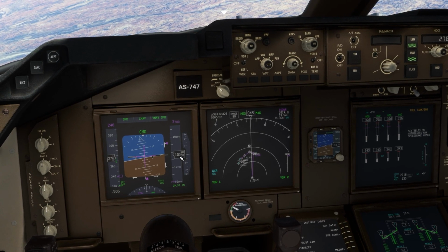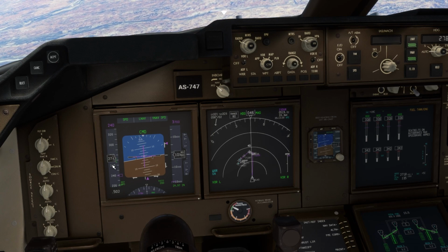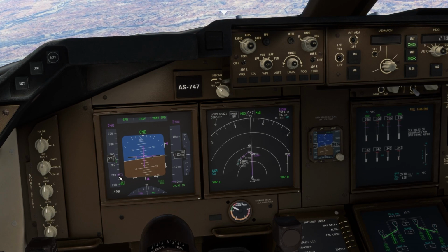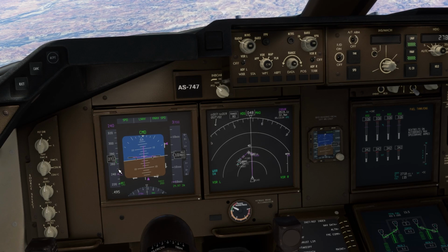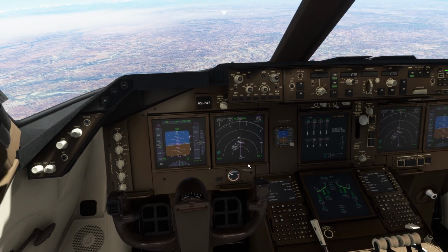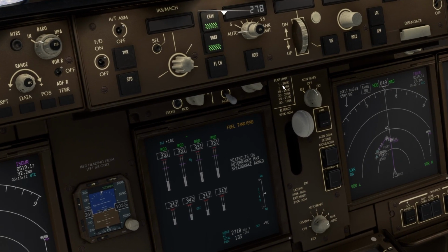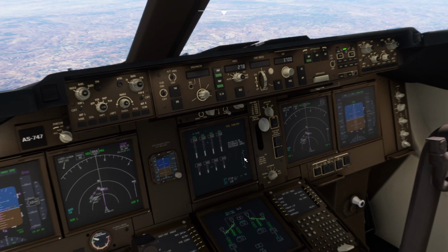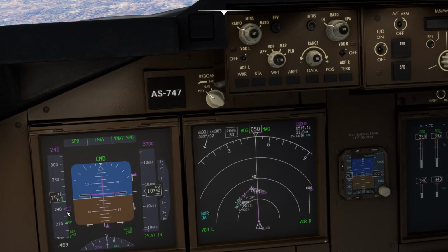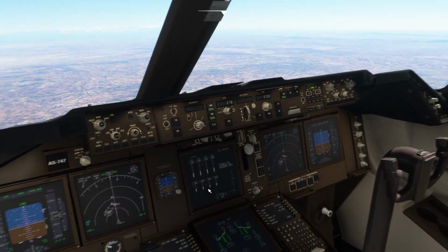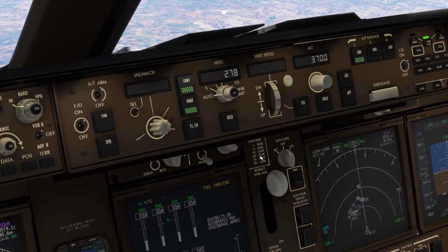Right now, as you can see, the plane is at 10,000 feet. That's why the speed is reducing, and it will be at 240 knots. And then once the plane is at 240 knots, the descent will start again. With this, I would just like to tell you the speed limits for different flap positions. At 285 knots, you can set the flaps to 1 degree, then at 265 to 5 degrees, 245 knots to 10. So right now, as the plane's speed is reducing to 240 knots, I can extend the flaps to 10 degrees because the plane will now be flying at 240.